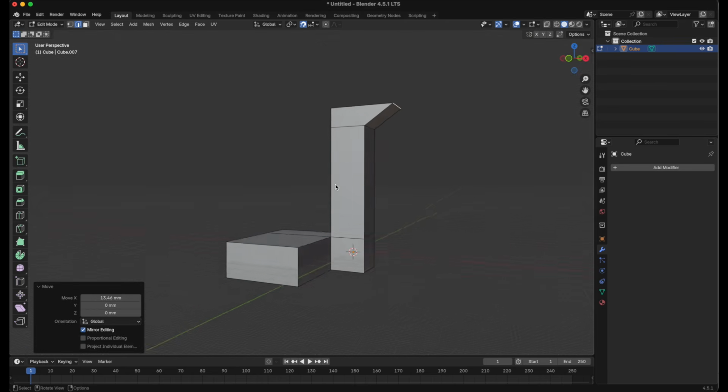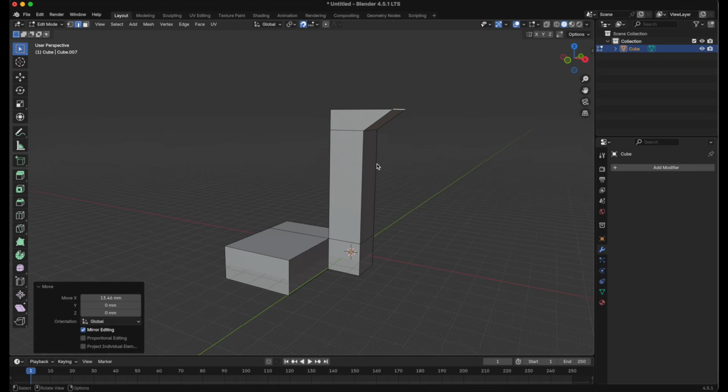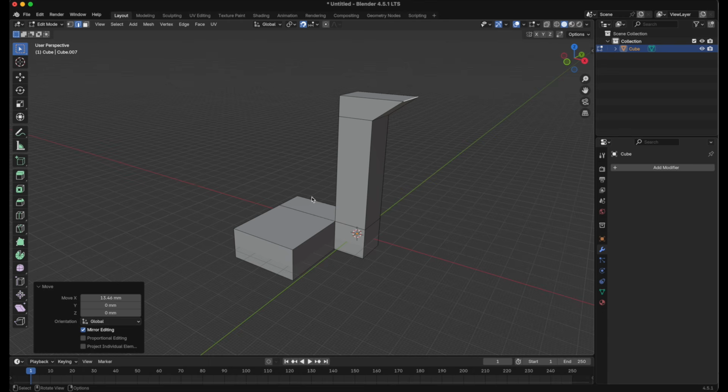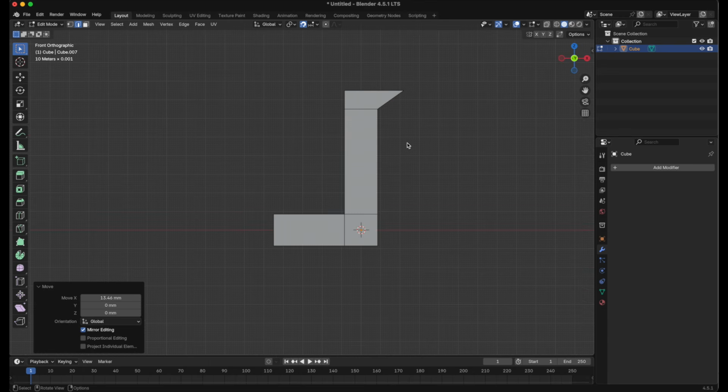how steep of an overhang can we have here? And remember, for this part here, for whatever reason, the design has to be printed in this orientation. We cannot move the orientation over. Well, in general, for 3D printing, an overhang of no more than 60 degrees is printable. And really, if you want a high quality